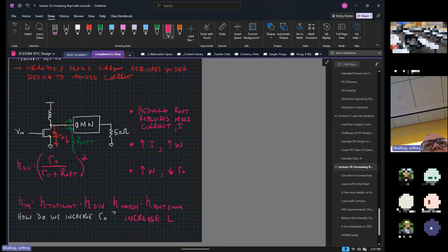Yeah, that's right. It'll improve gain. The output resistance will be higher, so it will improve gain. Anything else? Yeah. And it will basically decrease the headroom. Okay, it will decrease the headroom because VD-SAT is inversely proportional to W over L. Yeah, that's true. Anything really, really negative about increasing length?